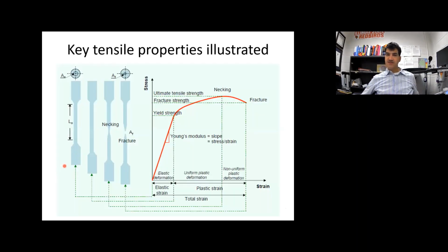All right, so once again, here is a stress strain curve, and here are a few points on the stress strain curve that are labeled, and a few regions that are labeled. So first of all, this linear region right here, I mentioned this before, but this is called the elastic region. And that's because in this region, we're getting elastic deformation. So if you were to stretch the part, say up to here, and then release the part, let it go, it would go back to its initial shape, just like a spring. And we know that because we've got elastic deformation. Elastic means temporary.